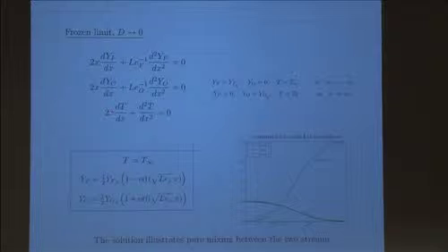But you can still solve this problem. The temperature clearly will remain constant throughout, but the concentrations of fuel and oxidizer will vary because there is mixing. So this limit essentially tells you that the fuel and oxidizer mix through this entire infinite domain. And you can see here the profile of the oxidizer, the profile of the fuel for different values of nu, I believe. This is presented here for equal Lewis numbers. In other words, the Lewis numbers of the fuel and oxidizer were assumed to be the same in these graphs. So this is an illustration of pure mixing.